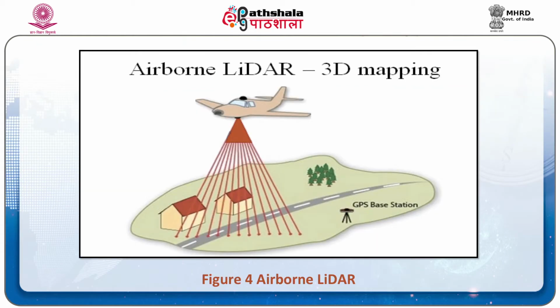The LIDAR sensor collects a huge amount of data, and a single survey can easily generate billions of points totaling several terabytes. An IMU is used to determine the attitude of the aircraft as the sensor is taking measurements. These are recorded in degrees to an extremely high accuracy in all dimensions as roll, pitch and yaw, the vertical and horizontal movement of the aircraft in flight.